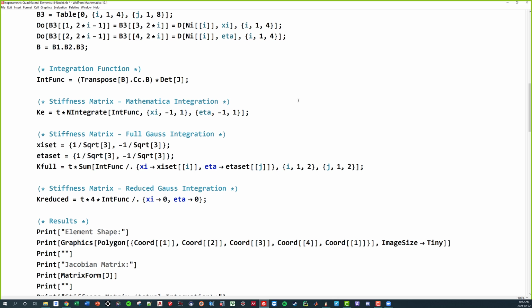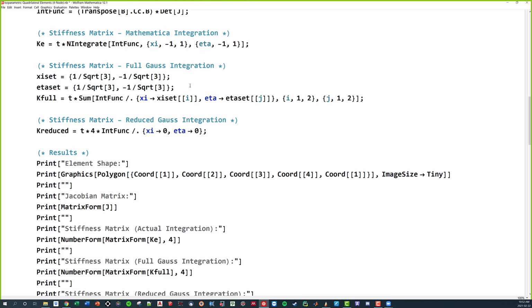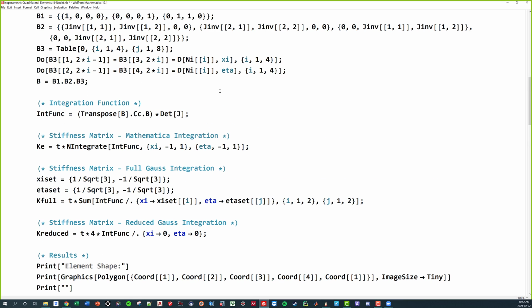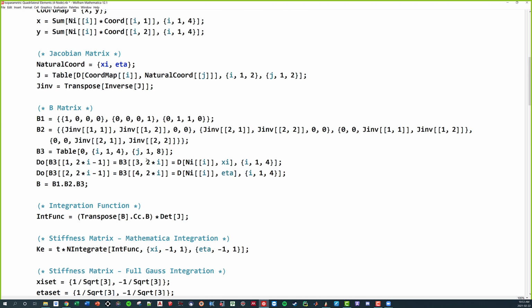So just to make sure, the actual integration is exact in terms of the integration. The problem is our approximation function is what leads to the errors, basically. So if we had a 4-node element, remember that we are approximating it using a linear approximation. And that's where the accuracy starts to go away a bit, because we cannot fully capture the behavior of the element just by using a linear approximation between nodes. The integration itself is just fine. It's simply integration.